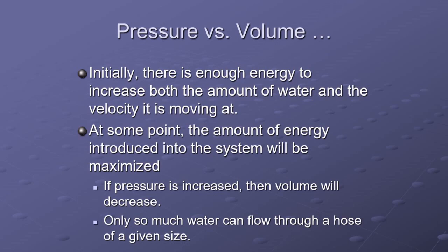If I need to have more pressure, I'm going to have to produce less volume out the discharges. That's not necessarily out the discharge of the pump. Actually, it is out the discharge of the pump, into the hoseway and out the nozzles. You might have to shut down more nozzles to give you more pressure. These things are inverse and they're very closely tied together. They're not entirely and exactly inverse, but they're mostly inverse once you're into a pumping operation.